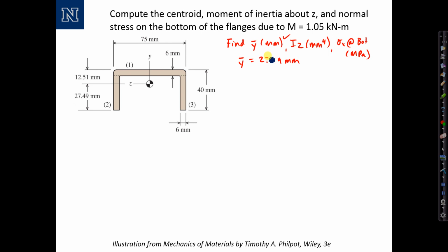We found the centroid in the last video, and it's denoted here on the figure. Centroid location is 27.49 millimeters from the bottom and 12.51 millimeters from the top. Next, we should compute the moment of inertia. In order to calculate the moment of inertia about the overall centroidal axis, we'll apply the parallel axis theorem.